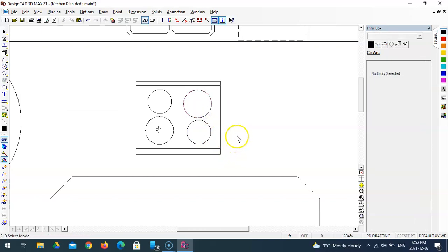We'll leave it there. Now, I have some garbage on my screen. This refresh button helps take some of that away. So if you click that, or regenerate, I guess it's called, it'll take some of that away. This oven needs a handle. Now the handle is going to be on the front, and it's going to be 1.5 inches thick. It's going to come here at an angle of 45 degrees and here at 135. So we're going to parallel that 1.5 inches out, 1.5 inches.